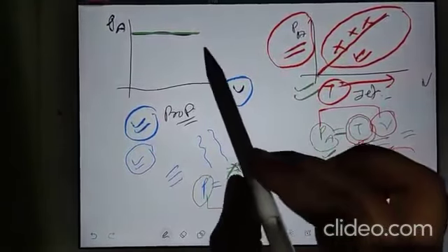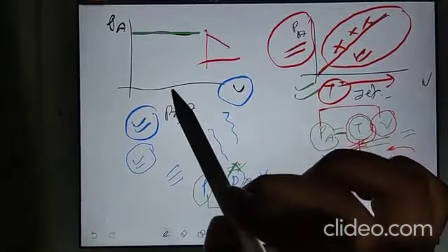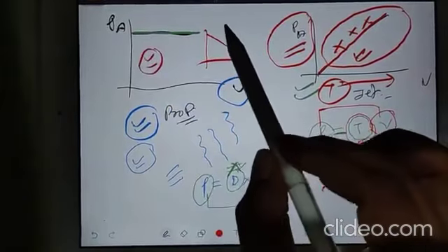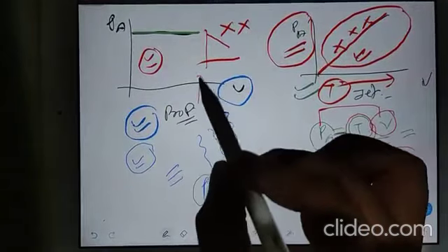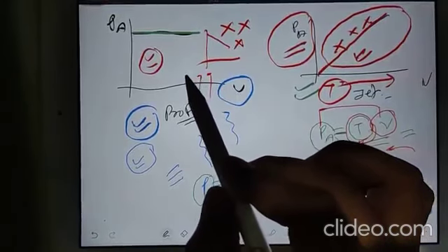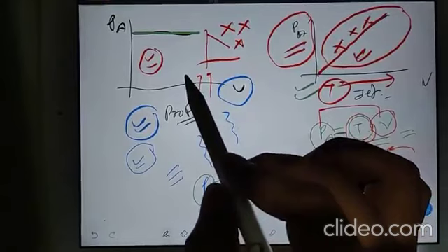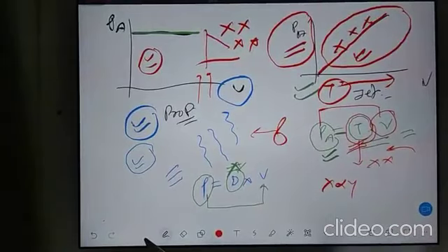And just opposite thing, here your thrust available is decreasing because it is propeller engine. And why is thrust available decreasing? Main problem is when you will go up on the altitude, you don't have enough density, so your thrust available depends on density.